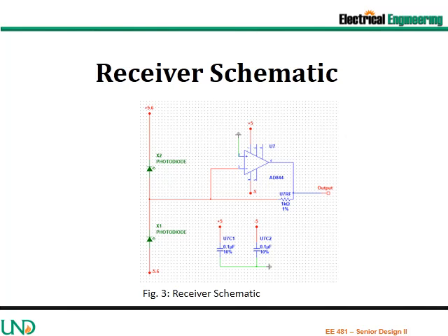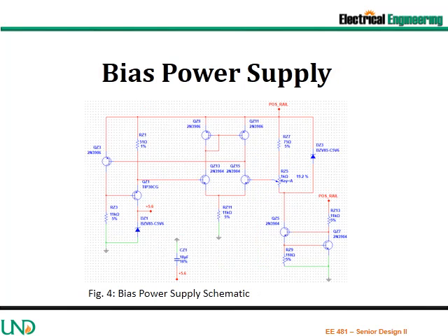As a note, the feedback resistor U7RF was changed to 33 kiloohms in the final product. The low impedance bias makes use of Zener diodes. Shown here is the positive bias, with the negative bias similarly configured.